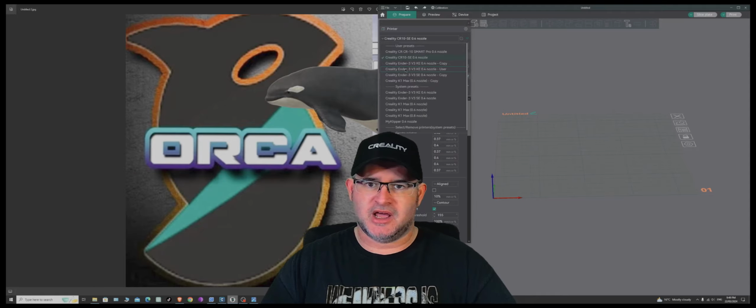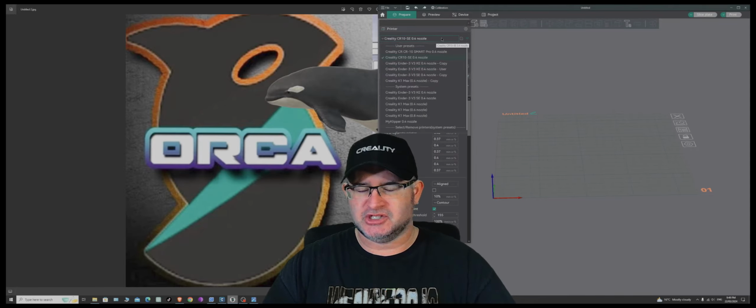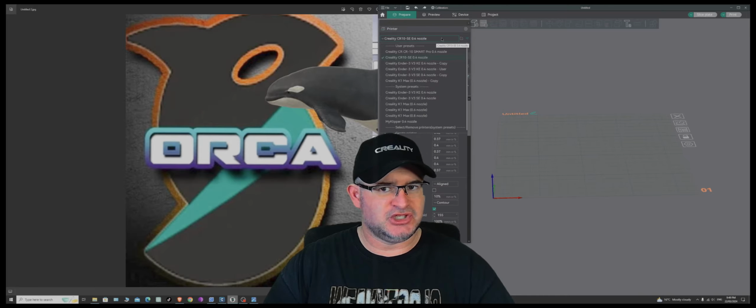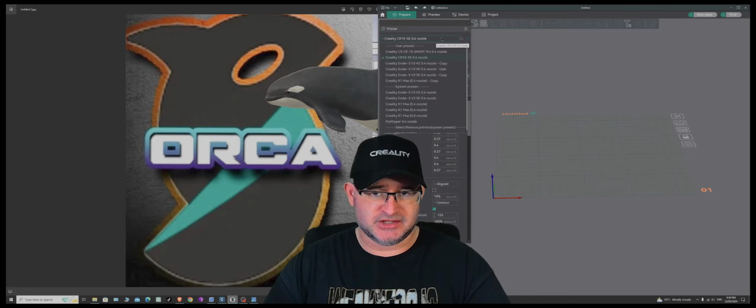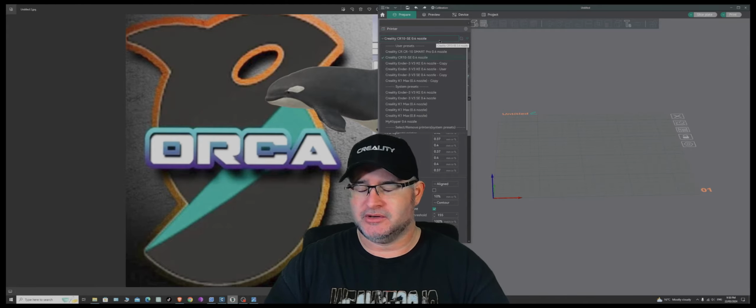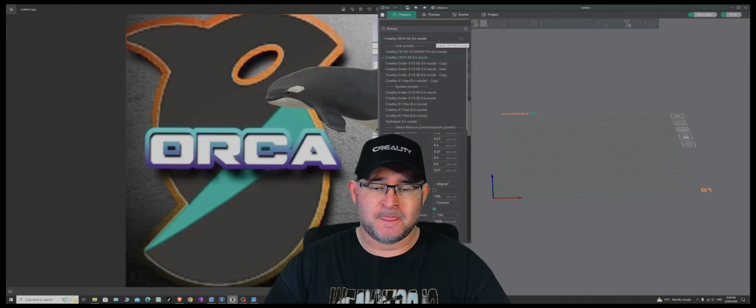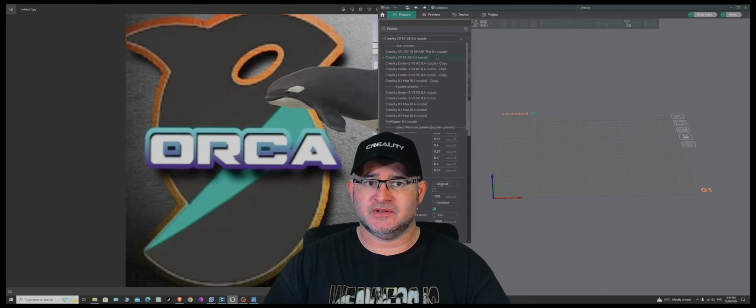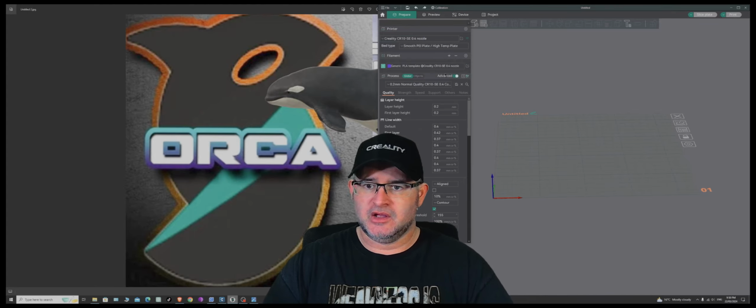So what we're going to do to start off with is walk you through how to add G-codes. Now every slicer profile has different G-code entries for start and stop. Not only do printers have different configurations based on whether they're a Core XY printer or a bed slinger printer, but they also have certain coding for the G-code that's exclusive to the slicer. I'll show you this, as you can see on the right-hand side, we have Orca Slicer.